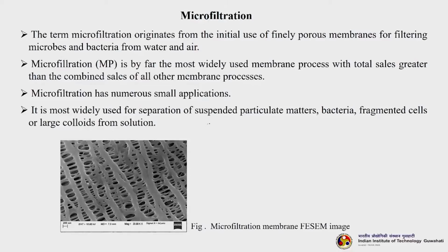Microfiltration has numerous applications. It is widely used for separation of suspended particulate matter, bacteria, fragmented cells or large colloids from the solution. You can see a FESEM image of one of the microfiltration membranes. You can see how the pores look, and you can observe the distinct pores. The pore size is very distinct and more or less very uniform.